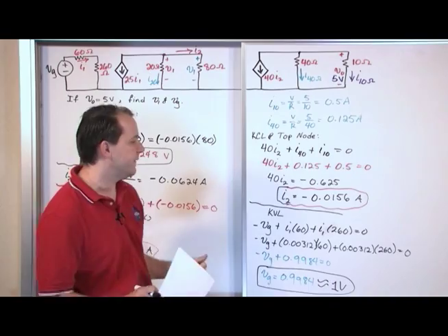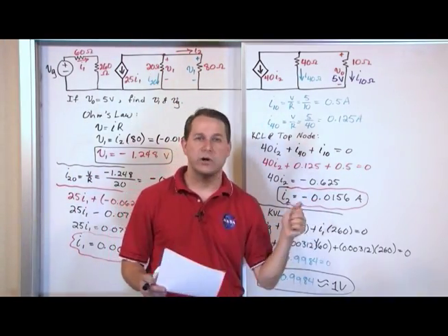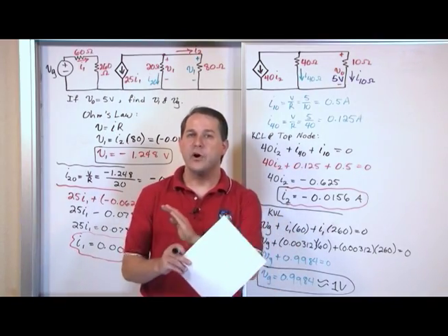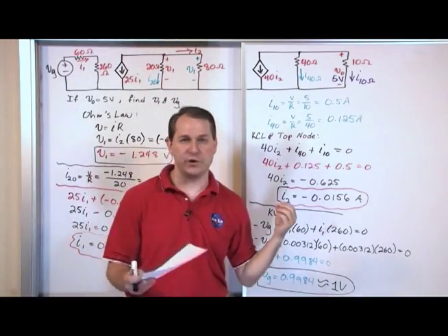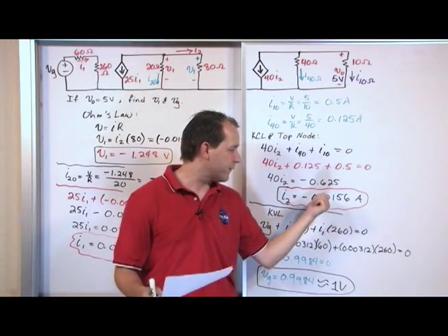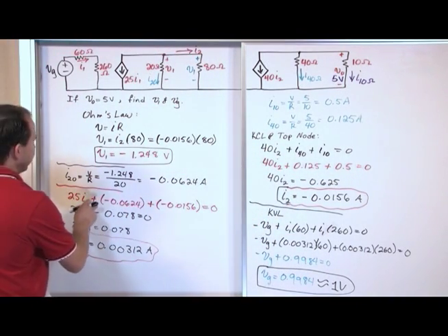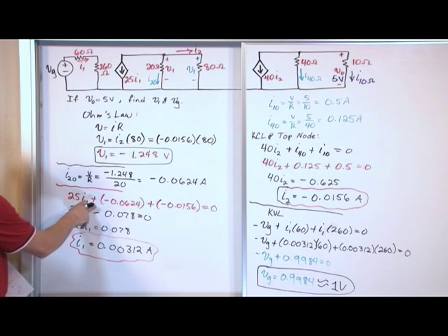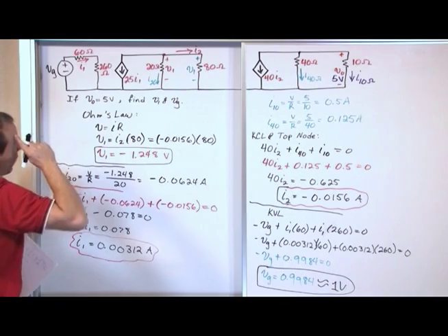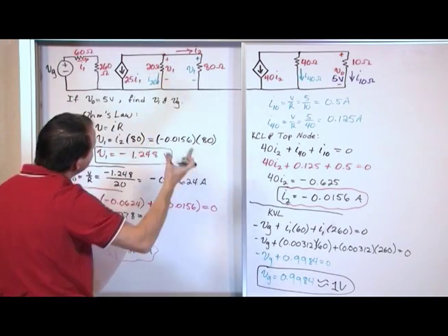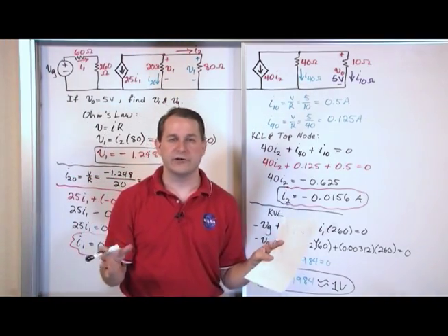The final thing I want to leave you with is something I've mentioned 4 or 5 times. When you realize that you have a negative current or a negative voltage that you've calculated, don't change your game plan. Continue to write your equations in the directions of the current that you've drawn on your paper, and then when you need to plug in for a value, you stick a negative in there. Resist the temptation. An excellent example is this spot right here. A lot of people when they're new, they try to write a Kirchhoff current law here, and they're like, okay, well, this current, I've drawn it this way, but it's really negative, it's really coming in. So they'll try to flip around their sign convention in the middle of the problem.